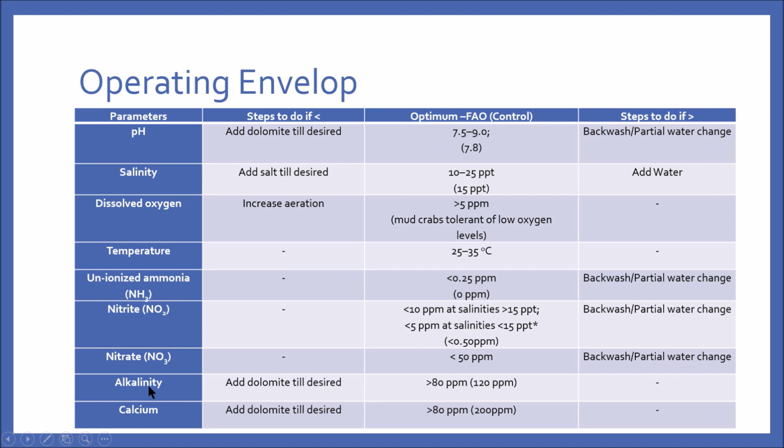Alkalinity. Alkalinity is what we call buffering capability, and ideally it should be more than 120 ppm. In the event that your alkalinity is low, do add in dolomite or even sodium bicarbonate to increase the alkalinity. With high alkalinity, your system is able to buffer against fluctuation in acidity. The key to controlling pH is to make sure that alkalinity is high.